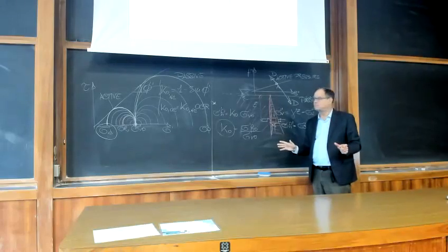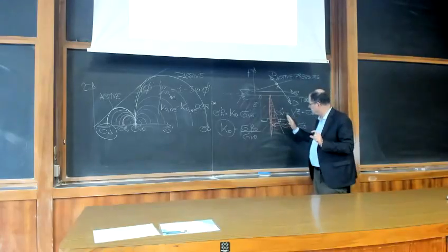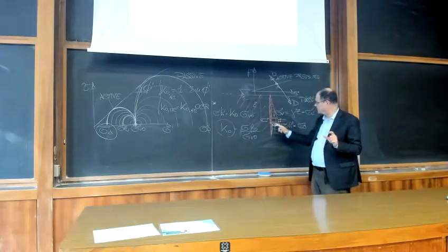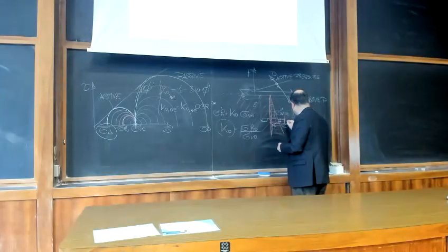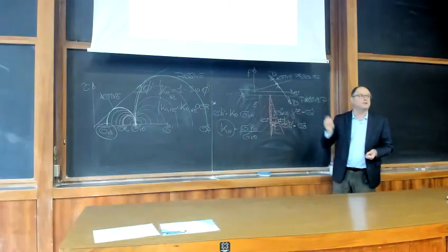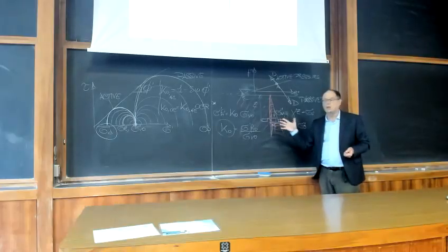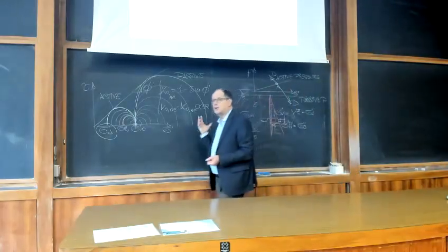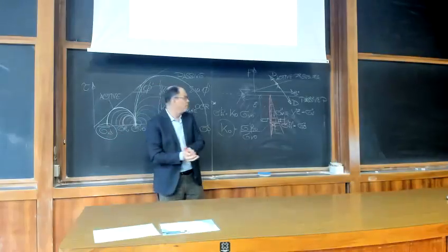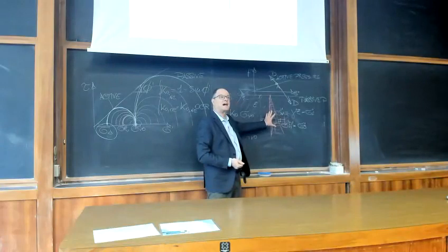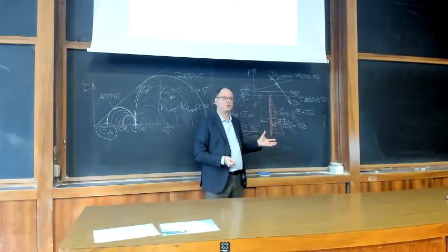Okay, so far? Now notice that if we consider this stress state, this plot, the resultant, as a possible PA, what we call the PA, the active pressure, in the first slide this morning, if we design this wall with this PA, we are essentially designing our wall with the minimum horizontal stress. So with the minimum force that can act on the wall. And this doesn't sound like a conservative assumption.